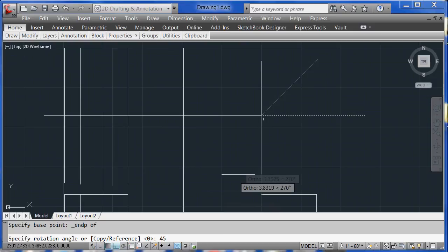If I did not, let me show you what happened. I'm going to turn off my F8. It'll go all over the place, okay? But as long as my F8 is invoked, I can make sure it maintains an orthogonal orientation, all right? So let's take a look at what we have here. Zoom, dynamic. You can type in zoom all or zoom extents, and it will basically give you this image here, or you can just, like I said, scroll with your middle mouse button.